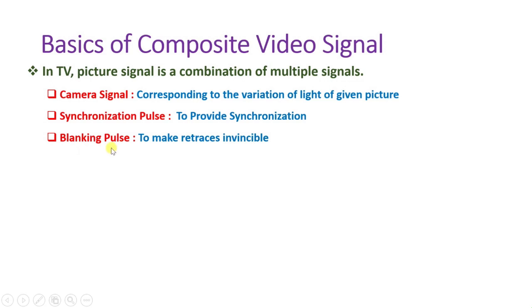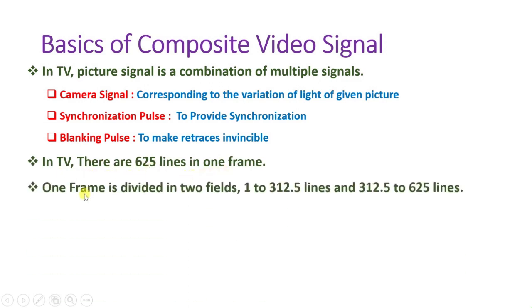Figure 7.2. Composite video signal for two horizontal lines. Once the blanking time is long enough to cover retrace, the blanking voltage is removed. Then the scanning beam is on the left, ready to scan the next line. In this way, each horizontal line is scanned successively. Note that the second line shows dark image information near the black level.